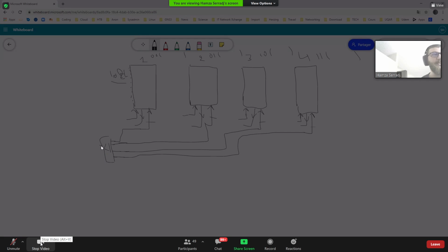So I call it a multiplexer, right? For my bus address, the width is 12 bits here, but it's going to multiplex on the first 2 bits to say which chip I'm going to go to first. Go here, or this, or this, or this, right? Just using these first 2 bits, I can select. So this one will be the address in reality: this one is 01, this one is 10, and this one is 11.